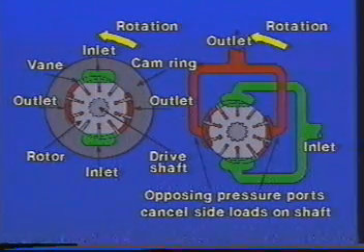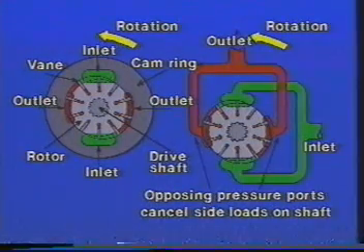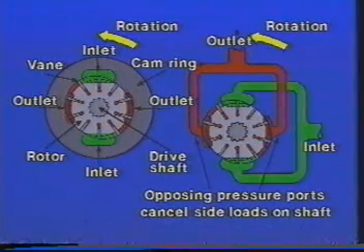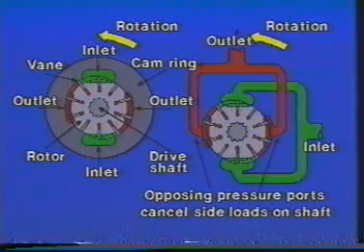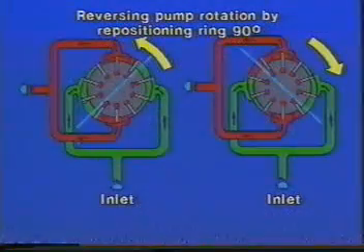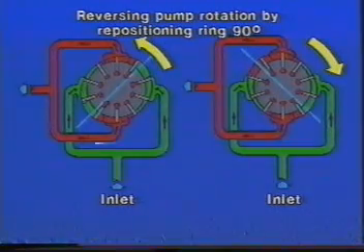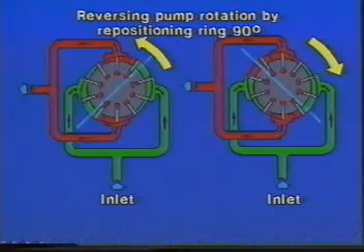However, interchangeable rings with different cam contours or widths are available, making it possible to quickly modify those pumps to increase or decrease their delivery. Another modification we sometimes require is to reverse the drive shaft direction. We would, however, have to ensure that the flow direction within the pump is not reversed.